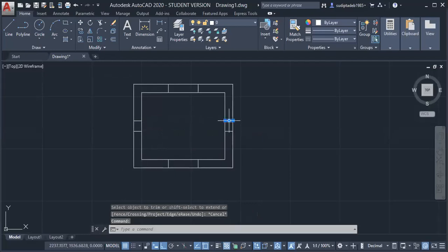Also I am going to trim these two parts because on this side there is a long offset distance you can get from the surface, it is above 20. So I have completed these two things, and these two. Now because we have to show the outlines, these are the outlines we have to show always. Next, what happens if we draw this side?